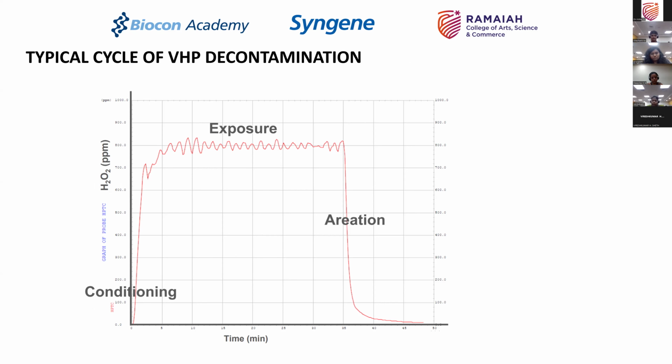If you say, I always maintain my room at 22 degrees centigrade, I do my sterilization always at 123 degrees centigrade, it will not work. You have to always specify a range, because today, with the advanced level of automation, things are different. In earlier days when I used to run manufacturing, we used to manually record data. There was limited staff, so we used to record the temperature once every 5 minutes and use it for, let's say, 45 minutes. So we had 9 readings and it was fine. Even then we could see a variation that would go up and down.